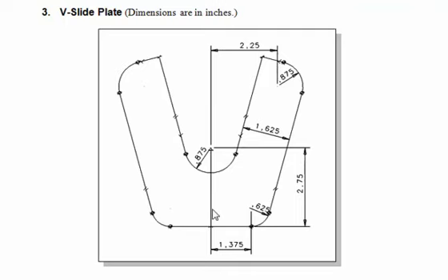For the design, there are three key locations, which are related to the three arcs: the arc at the center, the arc at the right, and the arc at the bottom. We will first create 3 circles at these locations. The concept of parametric sketching is that we can use the geometric constraint tools and the dimensional constraint tools to assure all of the implied geometric properties are maintained.